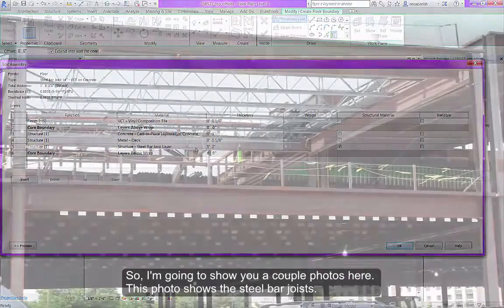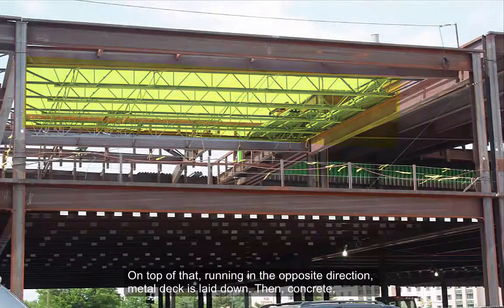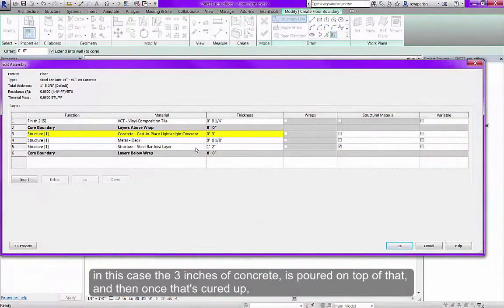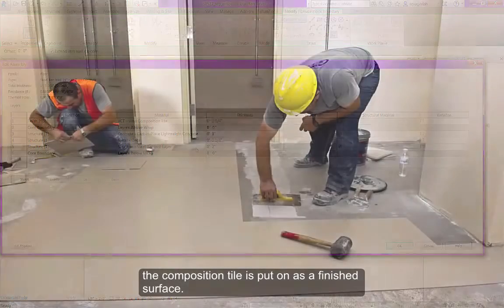So I'm going to show you a couple photos here. This photo shows the steel bar joists. On top of that, running in the opposite direction, metal deck is laid down. Then concrete, in this case the 3 inches of concrete, is poured on top of that. And then once that's cured up, the composition tile is put on as a finished surface.